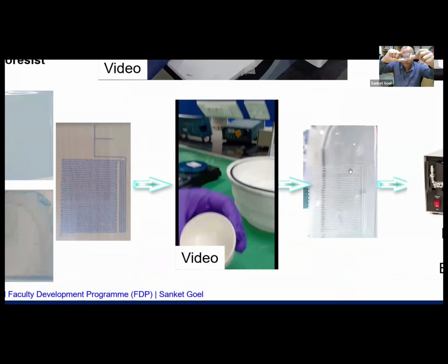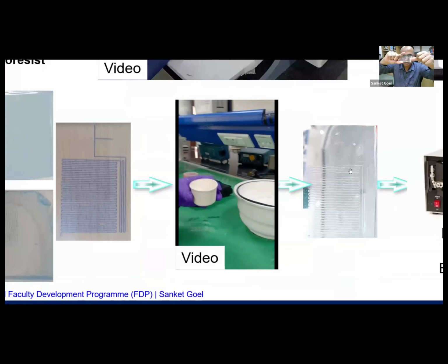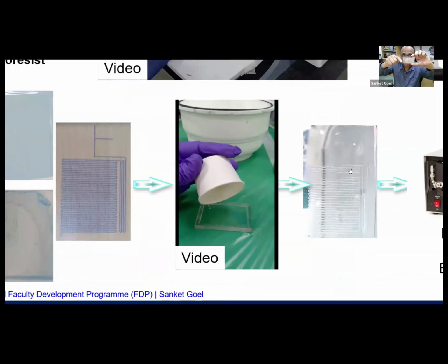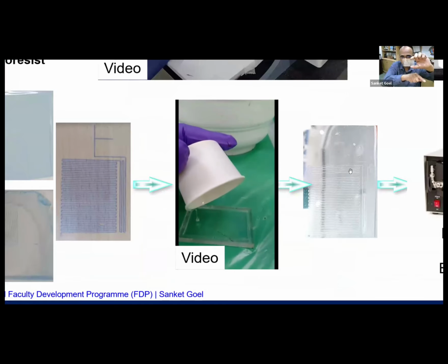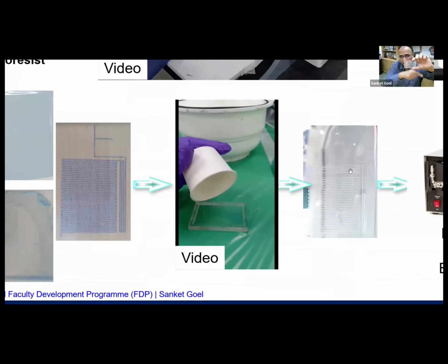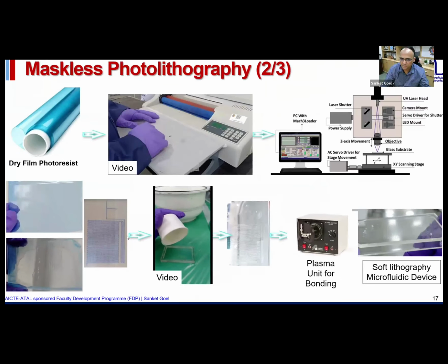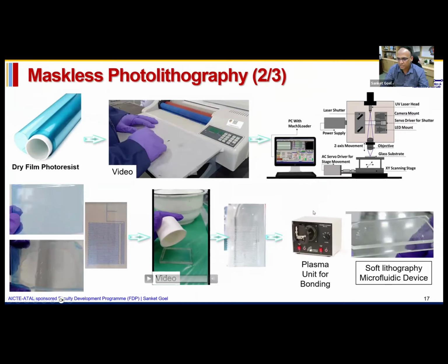You can see I've forcefully removed this PDMS layer from the glass slide. I would have done the same thing on the glass slide on the left, and I would have transferred the patterns onto PDMS. This way, I can use this device multiple times. I can keep producing these PDMS devices.